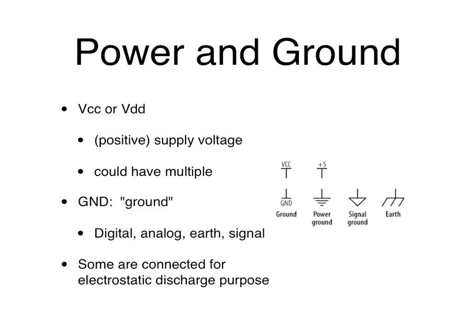Some grounds are really for electrostatic discharge, so earth, for example. I guess people nowadays might not worry as much about static discharge, but I had to worry about it. Before handling a chip, you had better discharge yourself, sometimes with a strap that's connected to metal ground or earth, so that when you handle a chip, you don't zap it and destroy it permanently.